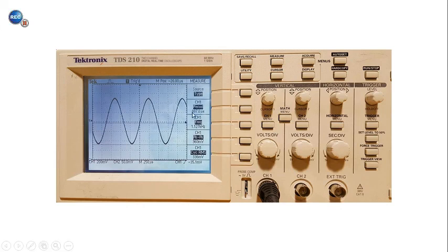And you can see that the oscilloscope screen tells us that the period is actually 887, so it's pretty close there, not quite exact. If we take 1 divided by 887 microseconds, we will get the frequency. The screen also tells us that it's 1.127 kilohertz. When I divided, I got 1.127 kilohertz, and so I got the same answer.